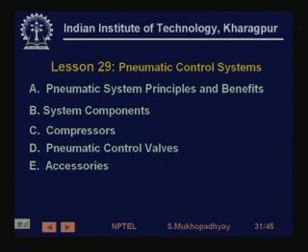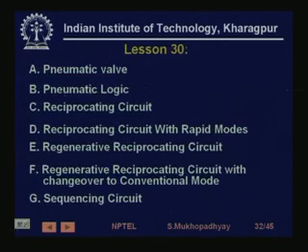Then we came to pneumatics. Pneumatics is very similar to hydraulics, but there are slight differences. So, we took a look at system components again, compressors, pneumatic valves and their accessories, and finally we took a look at pneumatic logic, and then various kinds of typical pneumatic circuits like reciprocating circuits with rapid retracts, reciprocating circuits with regeneration, so that the pressure energy is not wasted, and then various kinds of sequencing circuits.